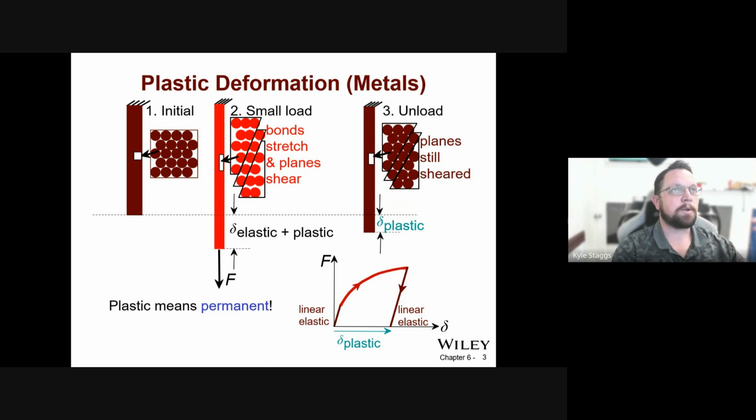And what you're doing by adding a load is you have the elastic plus the plastic deformation. And this gives you a slip along these diagonal planes. And this is exactly what was happening as he was forging that magnesium, for instance, creating conditions where you are causing slip along those planes.